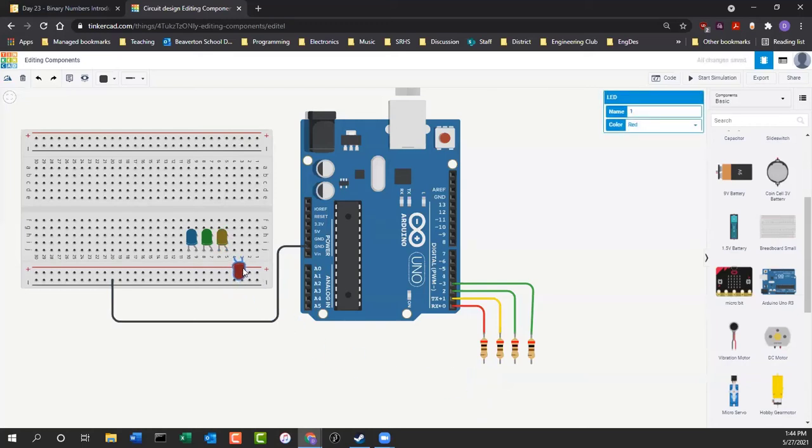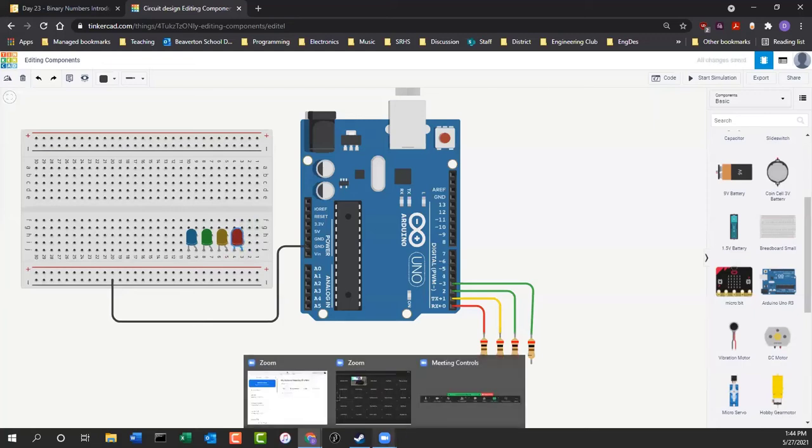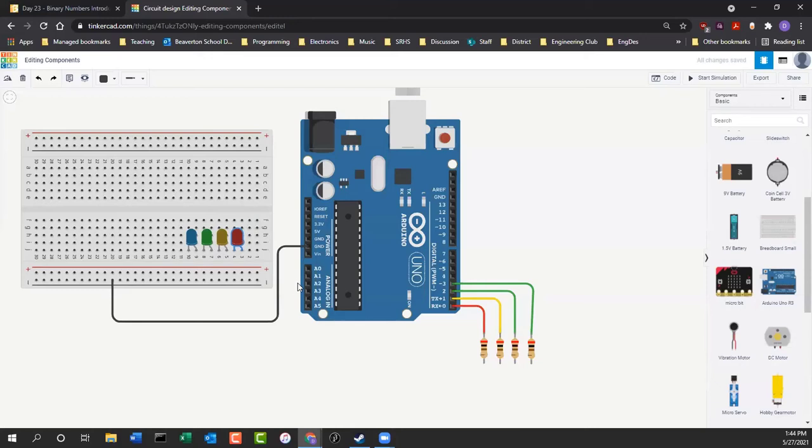If you remember, when we were talking about breadboards, we learned how they're connected. And so each of the wires coming out of the LED gets its own row, which is what we want. That allows us to treat them independently because we're going to need to do that. Now, we need these resistors to be connected to our lights. It's somewhere in the circuit. Doesn't matter where you put the resistor, before or after the LED. And the answer is it doesn't matter. You can put it before, you can put it after. It's still going to slow down the current.